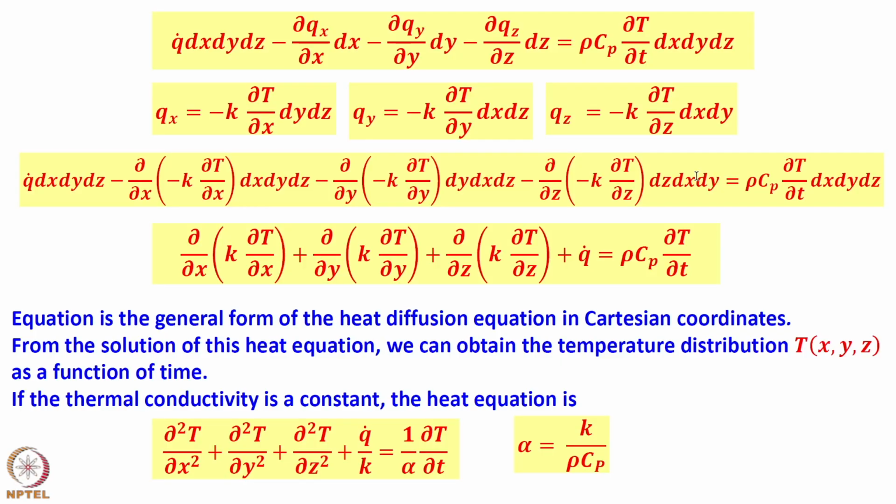No, it may be varying in that big range, but if you are operating between say 100 and 250 degrees centigrade, the thermal conductivity may vary very little, and it is okay to take it as constant within engineering approximations. So, k being constant is not a wrong approximation. We can use it quite effectively, and that is what is done here.